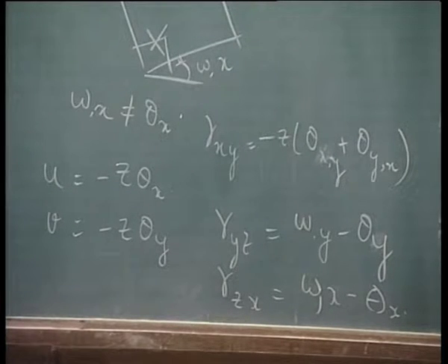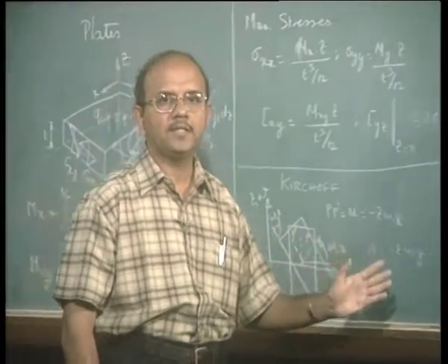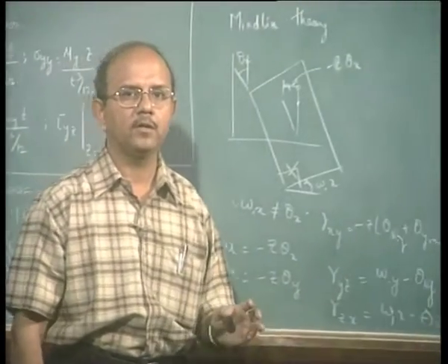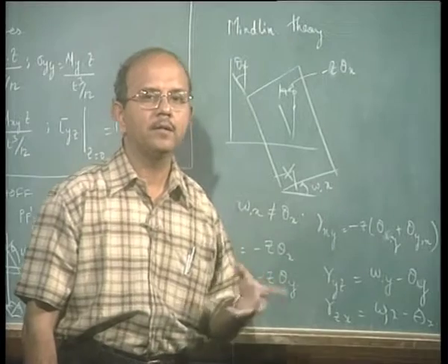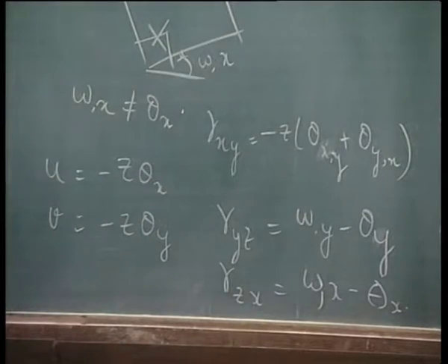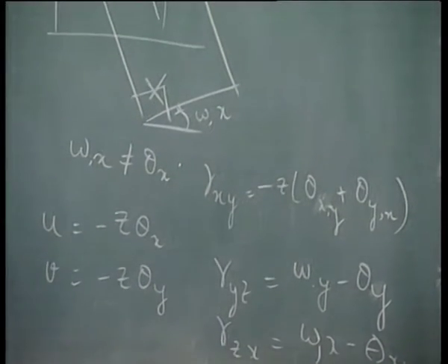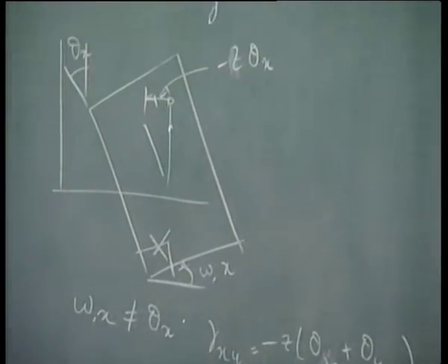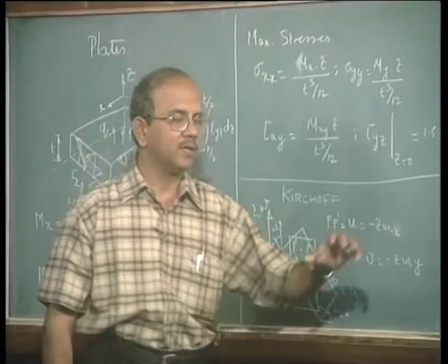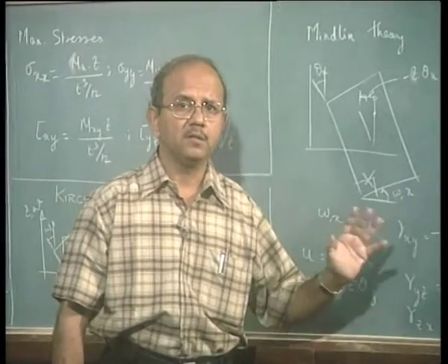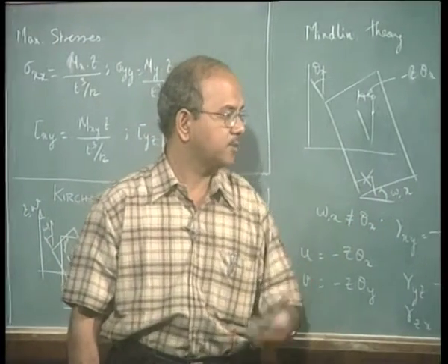But before we go further, have a look at them: Kirchhoff theory is applicable for thin plates where shear deformations are not important. Mindlin theory is one where shear deformations are important. There are elements which are based on Kirchhoff theory, Kirchhoff elements, and there are elements which are based on Mindlin theory, Mindlin elements.